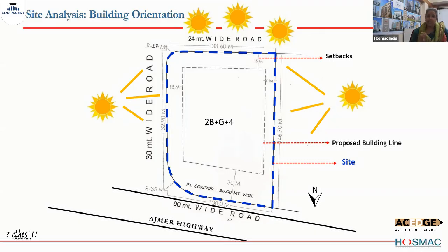So the annual site conditions with respect to weather need to be taken into account, one. Second is the soil condition of the land. We need to do soil testing to understand the soil bearing capacity, or how deep we can go. Is it a rocky land? All these studies come through soil surveys, land surveys. We need to get all this in place before we begin the design.